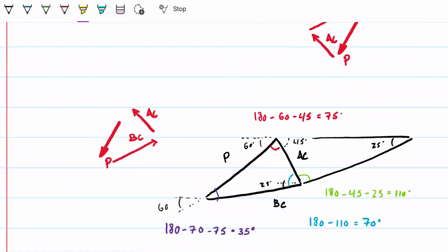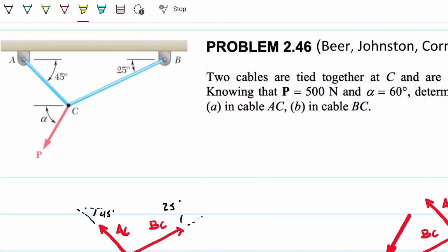So back to the beginning, back to the original problem when we were discussing this, we were talking about the forces, and we found that this tension here is the biggest tension, followed by this one here, followed by this one here, followed by this one here. So if we're going to do this triangle properly, we should have a very long side for AB, or BC, then almost the same size but slightly smaller one for P, and then a small one, kind of 300? So not exactly half, but significantly smaller for AC. That's how we build the triangle properly.